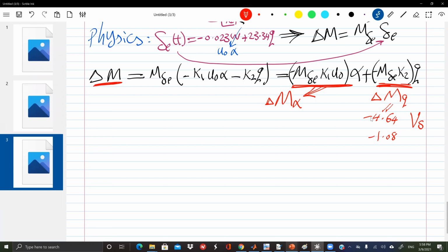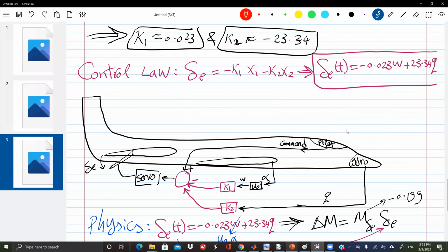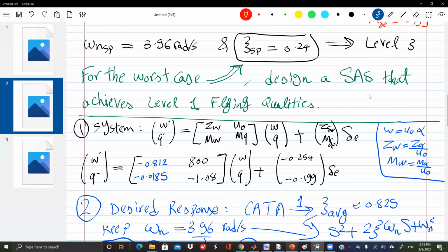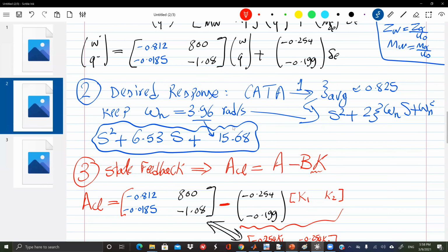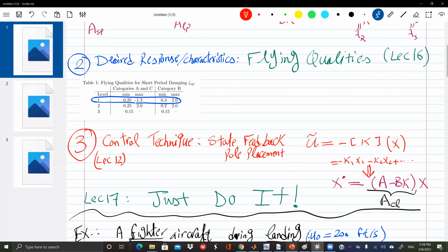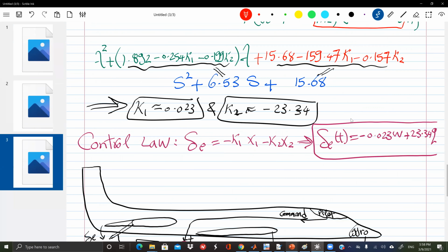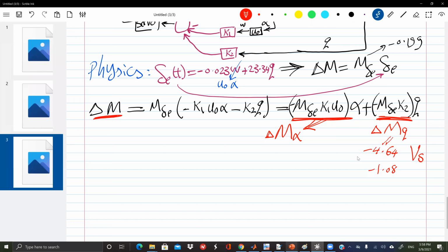And adding this extra damping, like 5 times damping, really brings the damping ratio from the 0.24, which was not accepted at all, to the 0.8, the value that I designed, which is in the middle of the range which will satisfy pilots. Any question about that? Any questions?